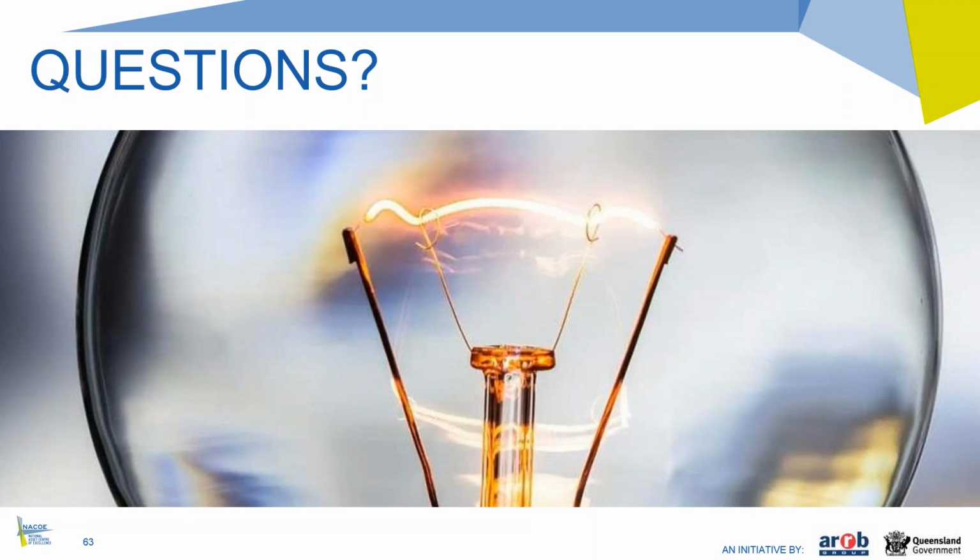Well, again, this is where we refer back to the original Shell method. Shell had shift factors, so the short answer is the reliability factor in the Austroads design method is supposed to account for that, because that was already part of the Shell method as well. So that's part of why you need a shift factor from laboratory to field.